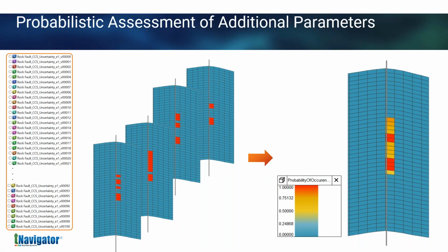And also moving forward, we can look at some geomechanical properties. So if you remember, Marcus was setting up some geomechanical properties, and that's included in the workflow as well. What we're mostly interested in is obviously caprock failure, but also at the injection site, you might be breaking, so-called breaking the rock, so rock failure. And in this case, we have used Mohr-Coulomb criteria. And you can see for 4 different cases here, we have some blocks that actually underwent this failure criteria. So these blocks have already done that, and they're flagged in red here.